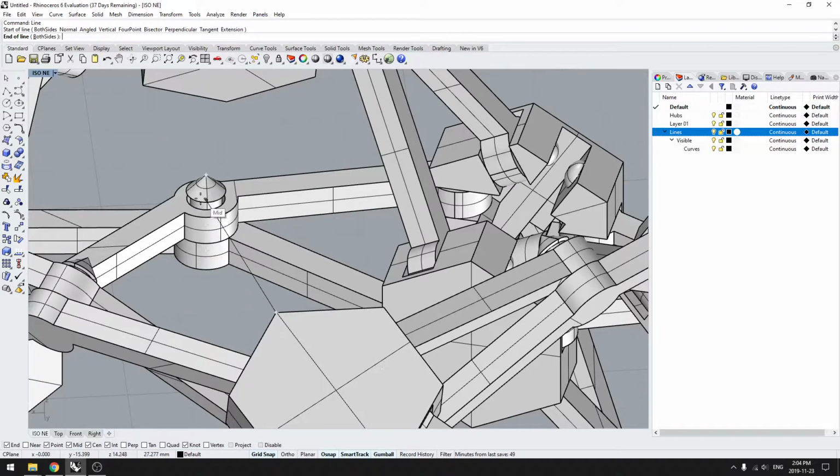So to skip over all this stuff and just select end, you can go down here, but usually you would just start left clicking everything, right? Which kind of takes a while. So instead of doing that, you can just right click on the one that you want. So in this case, I want end. Just gonna right click end, and it cancels all the rest.